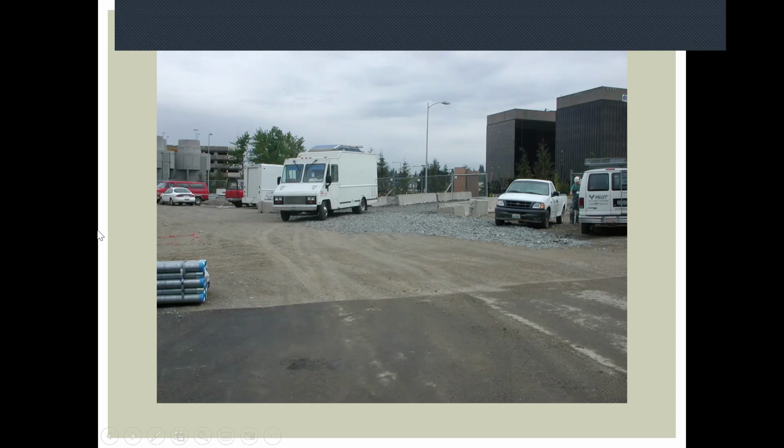A lot of things occur where nobody's thinking, nobody's putting two and two together, I guess. So maybe the plan sheet shows a rock construction entrance in some location for some distance, and then that's it. Somebody didn't communicate that we're going to be putting asphalt down next week. Connect the dots and run the rock right to the asphalt so that vehicles can stay on some material rather than dirt the whole time.